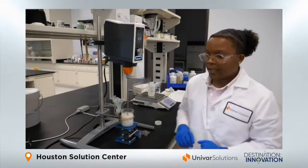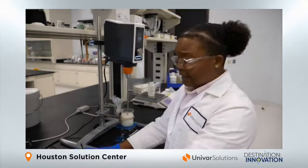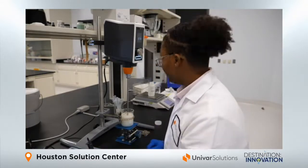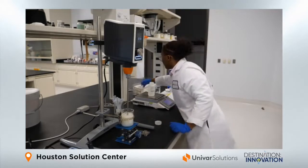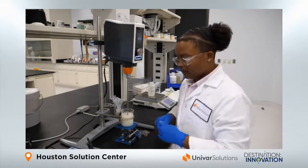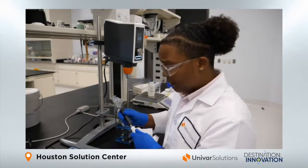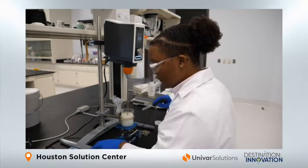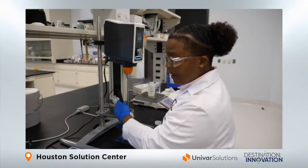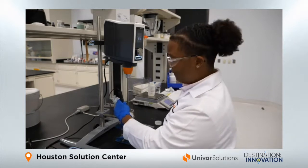So we have our pH meter over here, which I've already calibrated, and it is sitting in water. Dry off the excess water here, and then insert our probe. So right now our pH is about 5.6, and we're going to gradually increase to 7.5.